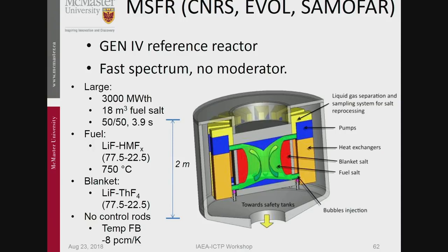Yeah, that is something that you should realize. If you have a small reactor with a strong negative power coefficient, or temperature coefficient, then just by changing the load, you can control the reactor. Because if you take away the load, it means that the temperature coming back into the reactor will be higher.